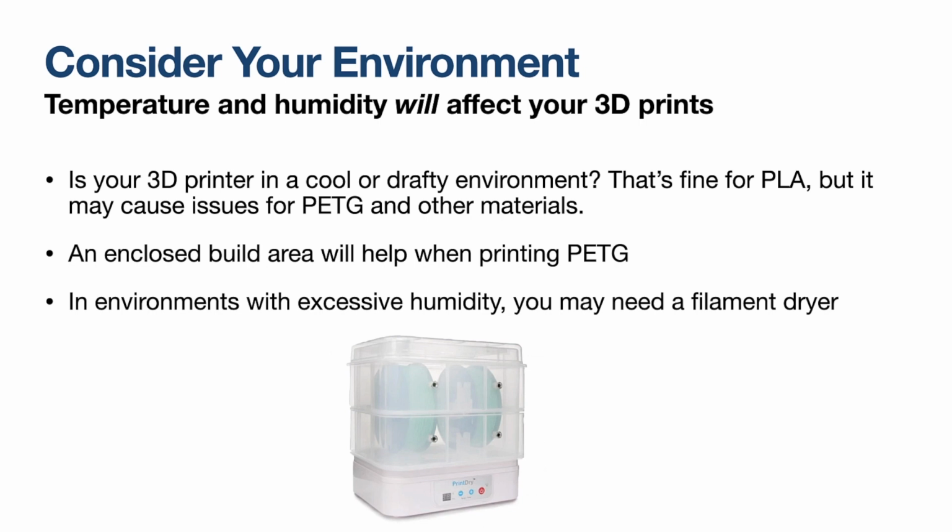And if they pick up too much moisture, you're going to have lots of printing defects. You'll get popping and hissing sounds while it's printing. You might see little steam escaping at the nozzle, and it's going to lead to gaps in your layering and surface defects and quality issues. So make sure that your filament is nice and dry.